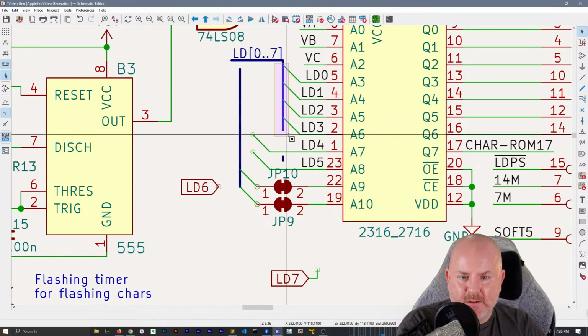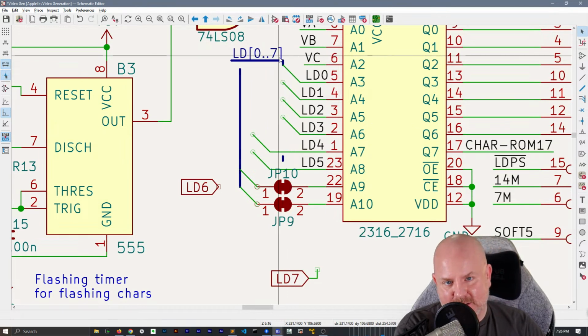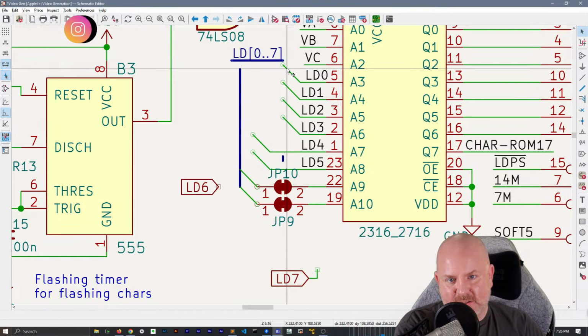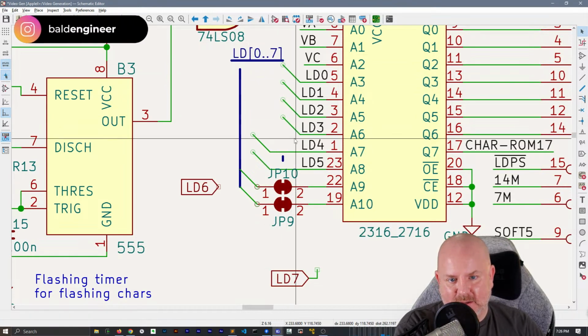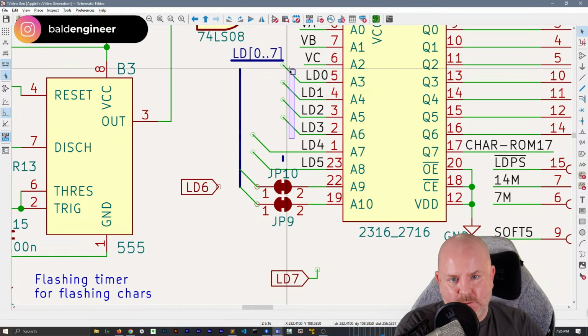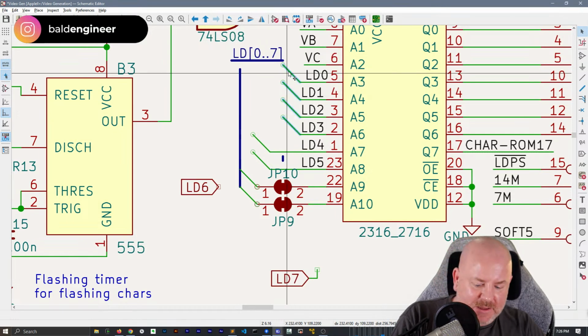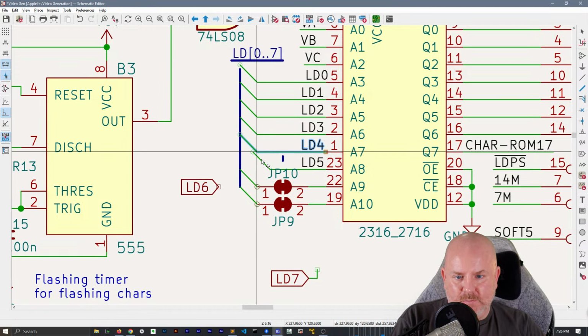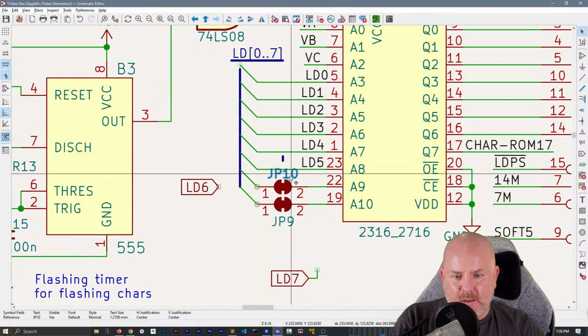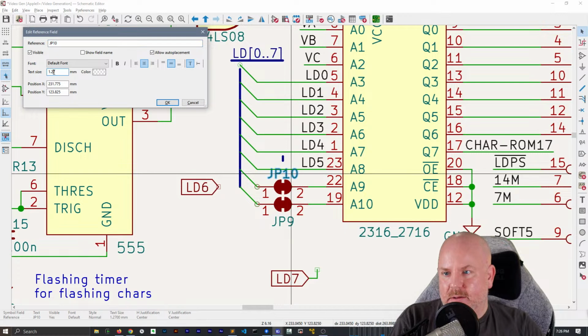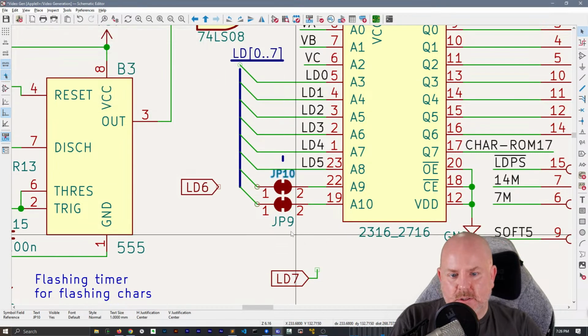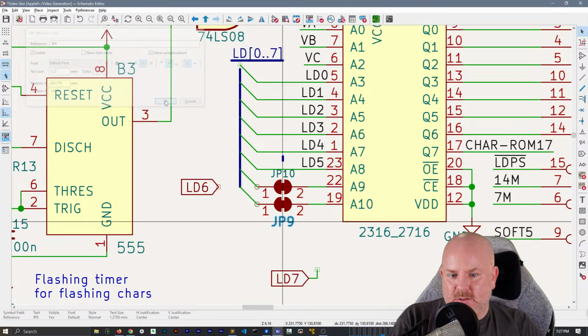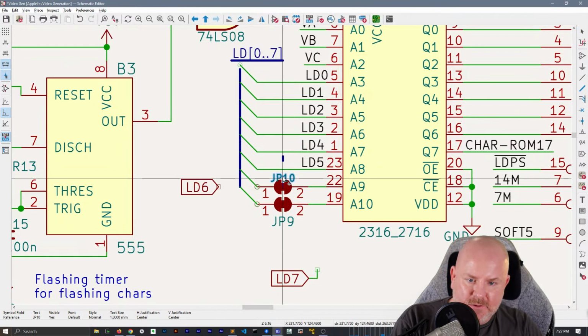So I'll use a drag to the right so that we can highlight multiple things, but only things that fall within the selection will actually get selected. That way I don't accidentally select things I don't want. Now I'll use drag to the left to partially select things, so anything that touches gets selected. Because then I want to move this all the way over to here. And we'll move this one, and this one. And then we're going to make this text 1 millimeter, and make this text 1 millimeter so it matches. And then we can move that down.